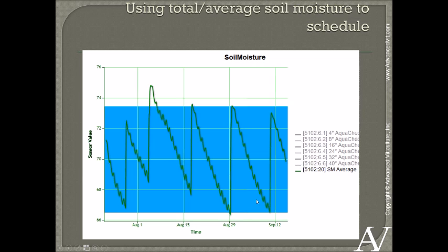If I want to, I can stretch this out and make it go into a deficit and go to a lower water content in the soil, or I can push them closer together and make it go up. That's where we have the control. And the closer we put these irrigations together, the more control we have. So that means a lower volume, more frequent type of approach.